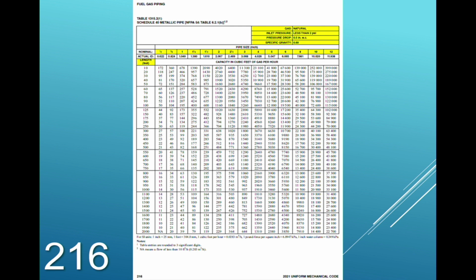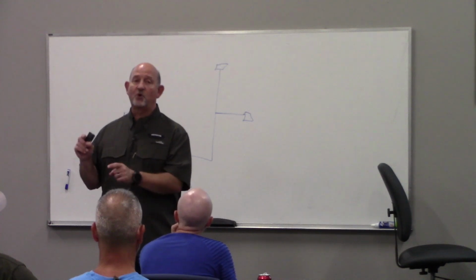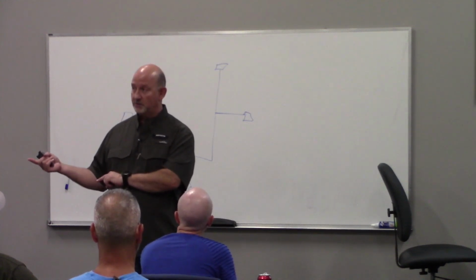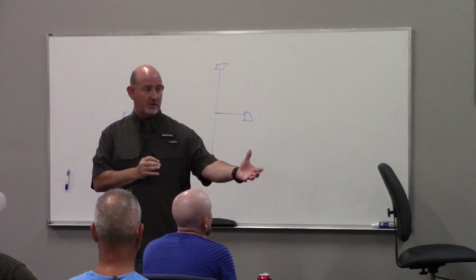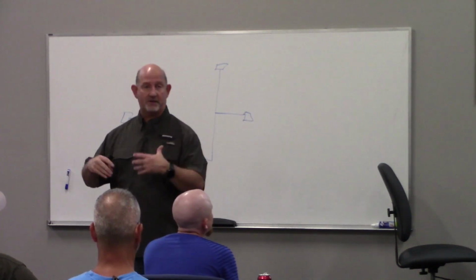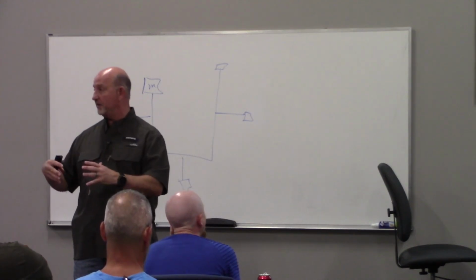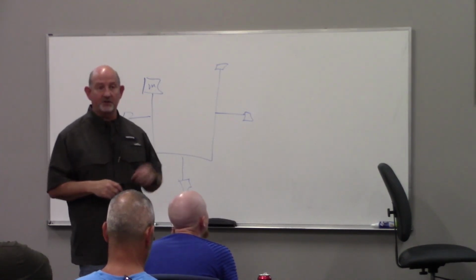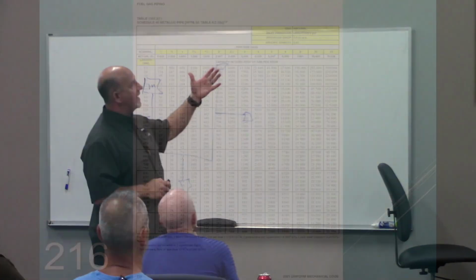Do you see why we've got to convert those BTUs into cubic foot? Now, I don't want to distract you, but if they do ask you a question about propane, propane is in BTUs. The table back there on propane will say capacity in BTUs. This one says capacity in cubic foot, right? That's why we had to convert our BTUs into cubic foot, right? Divide by 1,000 per the test, okay? So now we're going to plug that data in.